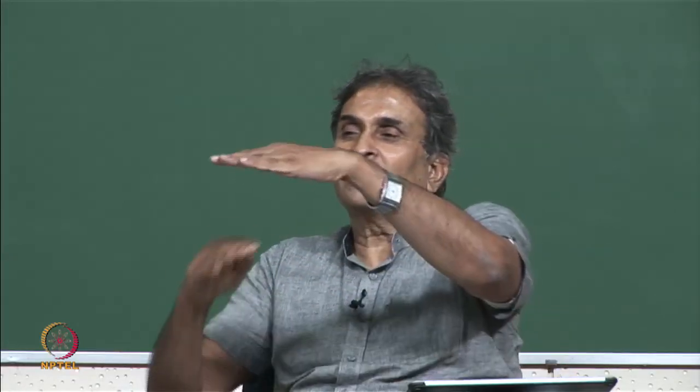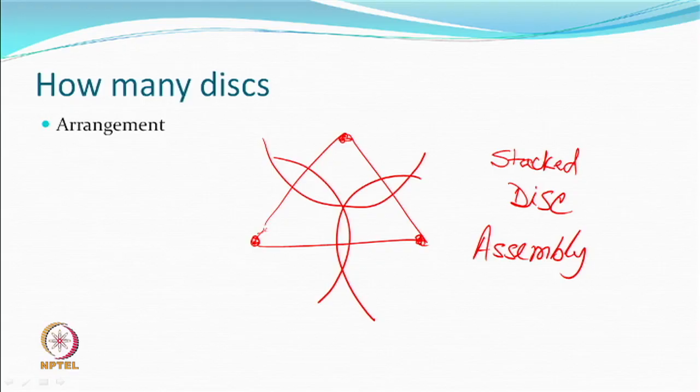So, yarn cannot just pass through without touching any one of them. The yarn has to touch, and one disc is here, the other is here. So, it goes from one to this, from here it can go there and then go here, then go there and come down. So, yarn is not going to move straight, it is going to move over the disc surfaces as it moves from one end to the other end of the stack, all right. So, equilateral triangle, obviously diameters of all of them may be same, material will be same, number of discs could be obviously 3 or more.